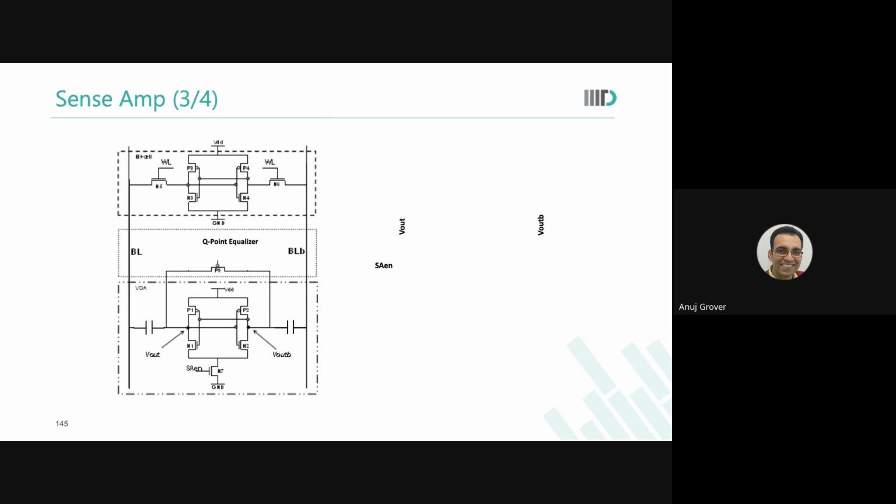Why? Because the sense amplifier is a turbo engine. It would consume a lot of power. If somehow I can reduce only the sense amplifier voltage without impacting the bit cell, I can reduce overall power consumption. Are you able to see that? So that is the advantage, where instead of coupling through a resistance, and a MOSFET is a resistance, I've coupled through a capacitor.